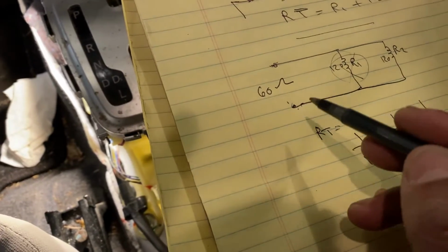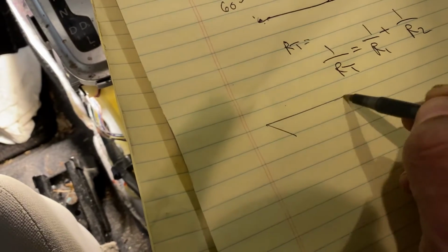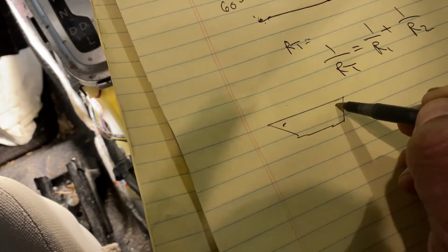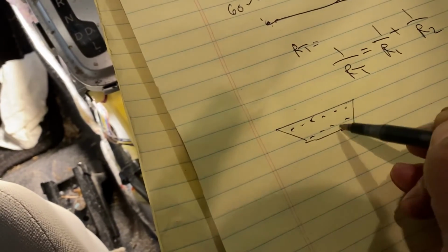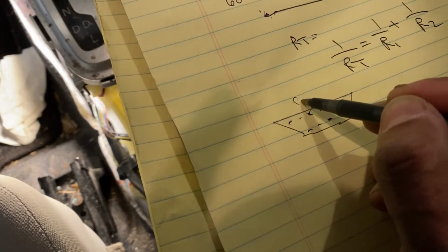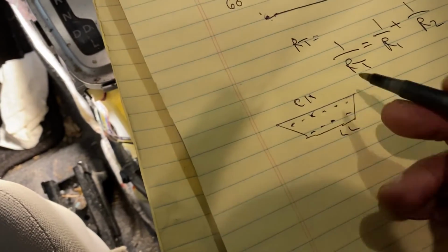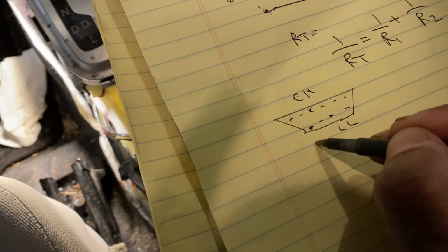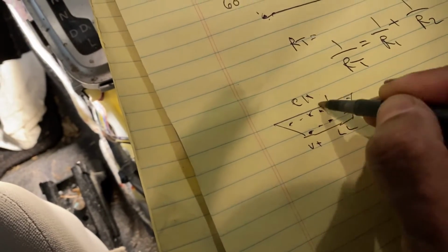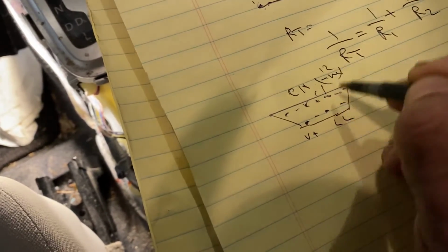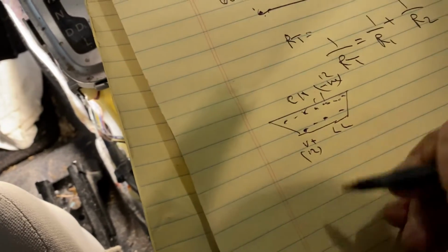So in this case, when you measure at the OBD port, pins 3 and 13 are supposed to be your CAN high and CAN low. Pin 16 is the positive power, and pins 4 and 5 are your negative, 12 volt. Okay, we're going to measure the CAN bus from this side first, and then we're going to take out the airbag module and measure from the socket.